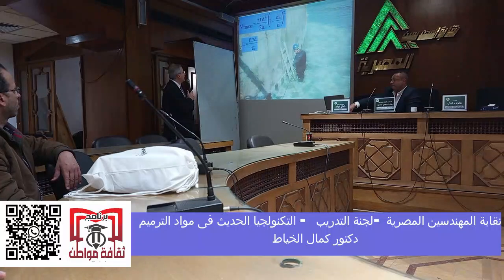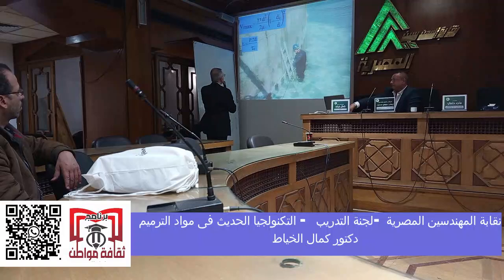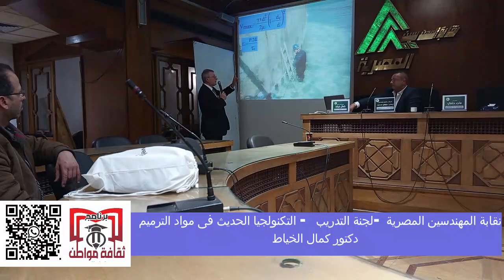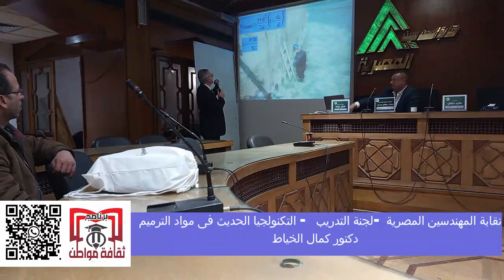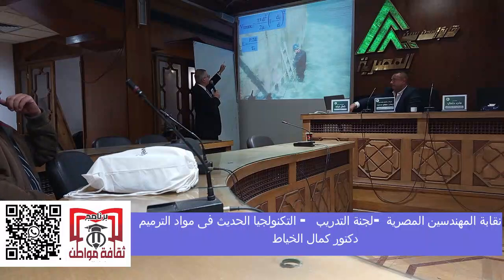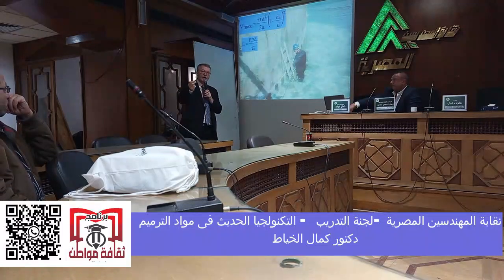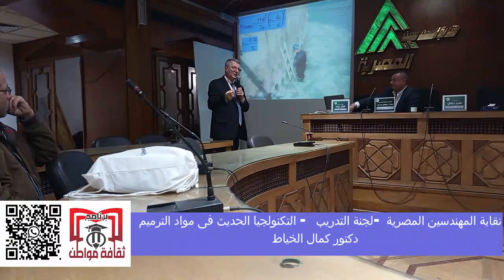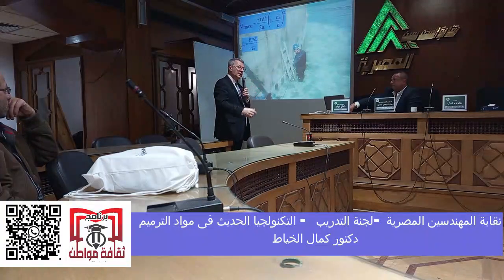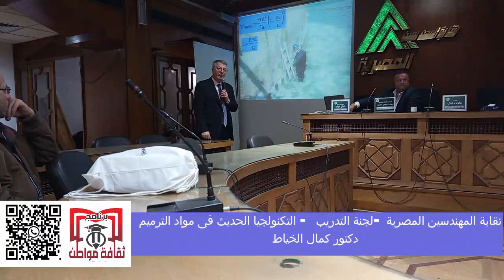So as this guy is injecting, he is thinking of the physics, let's go with physics. The maximum velocity of penetration of the grout is dependent on 1 over mu. Mu is the viscosity. So that's why you have to have low viscosity. If you have low viscosity, the speed of penetration is going to be higher.